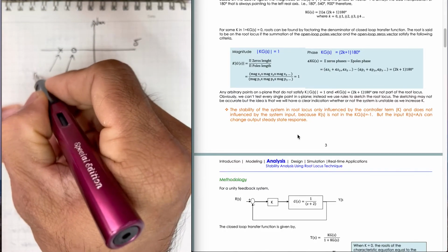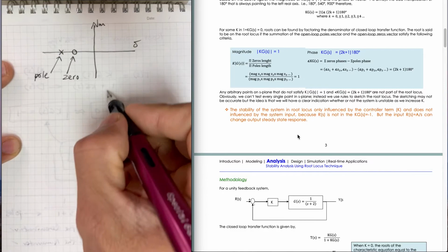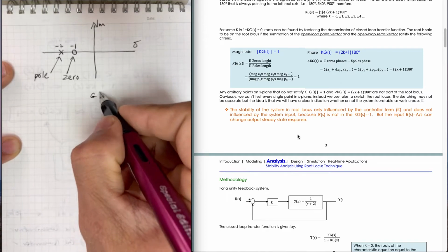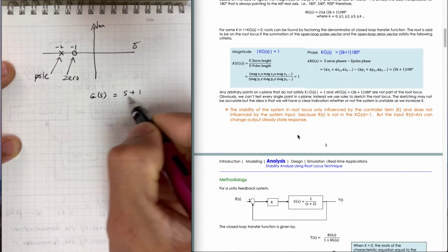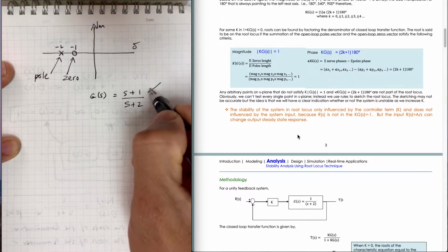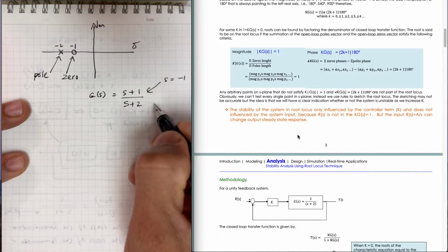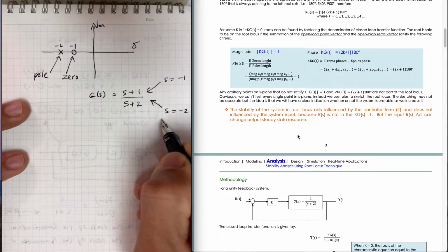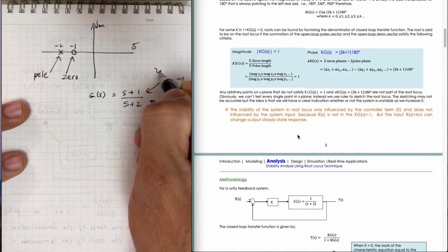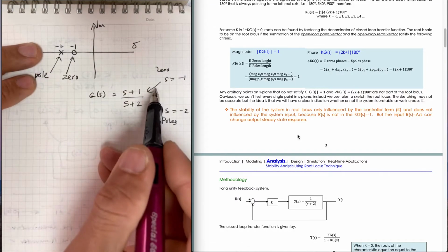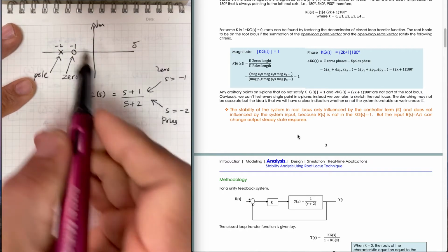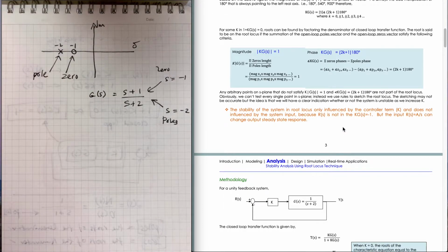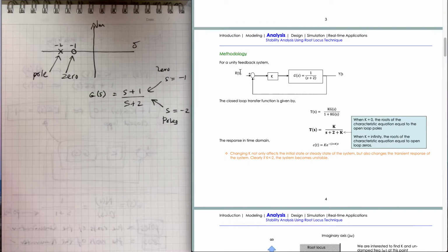This is poles. Assuming that our transfer function, this is, let's say, -1, -2, is getting from our transfer function as s plus 1, s plus 2. So this is our poles, s minus 1, our zero. This is our s equal to minus 2. This is our poles, right? This is our zero. So then we can plot like this, because 0 minus 1, right? The symbol for zero is O, and the symbol for poles is X.